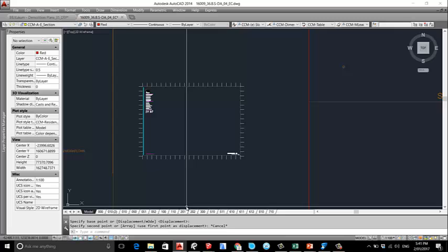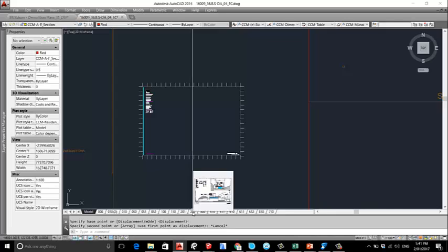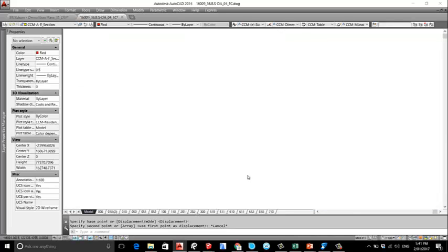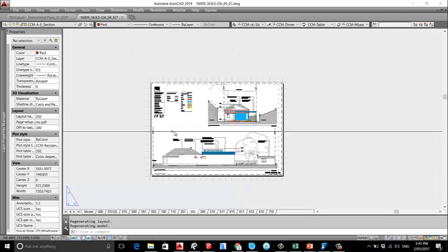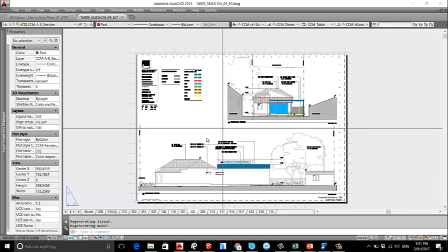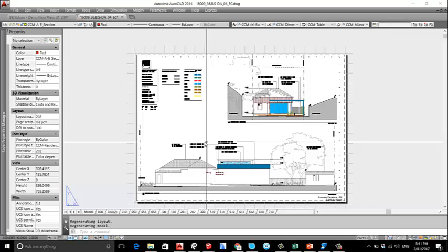So as you can see, the idea is to set the layouts kind of in order and try to touch them as little as possible. So then we know that they will print because we have the layers set up and the colors and the CTB all set up.